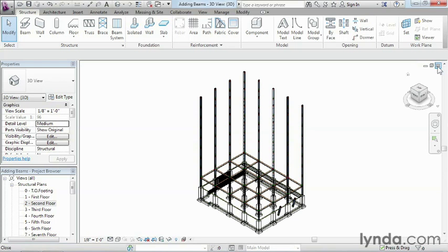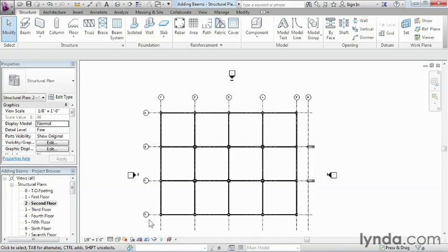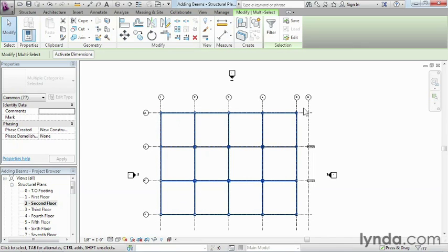So in order to be able to accomplish that, we're going to go back to our plan view, and you can either do that by double-clicking here on second floor or just closing this window down. And if you move your mouse down here to near where this D is at, don't actually click on anything, but just sort of click in space, hold your mouse button down, and just window around all these different entities that are here. Let go of the button. Everything will turn blue.